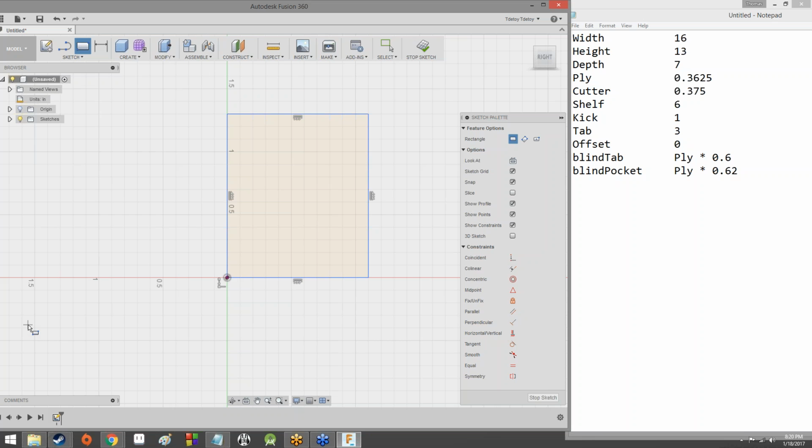What I mean by that is Fusion 360 specifically requires explicit dimensions to everything that you draw on it in order for it to be considered valid, because it wants to make sure that all those dimensions check out and nothing overlaps or floats out in the middle of nowhere or anything like that. And you want to make sure of that too. So for that reason, they introduced basically a restriction or a requirement that you dimension everything in order for it to be considered a valid drawing.